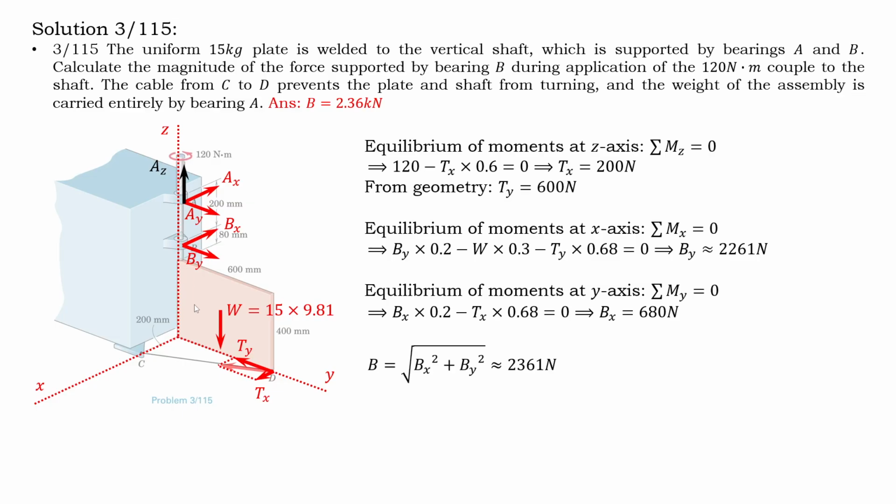So you can also do another thing. You can find the moment of all of these forces about point O, the origin. And then the result will be MX i plus MY j plus MZ k. And then you can put it equal to 0.